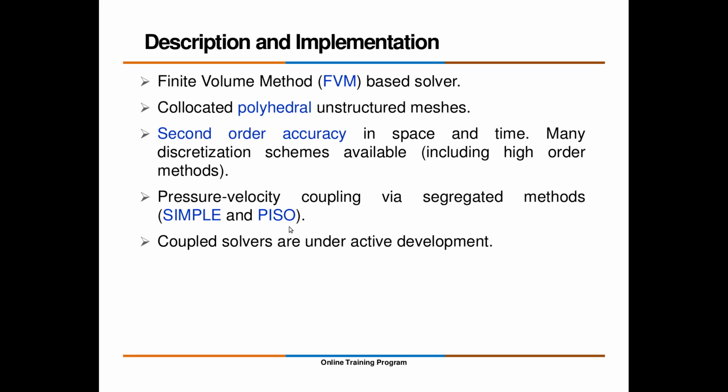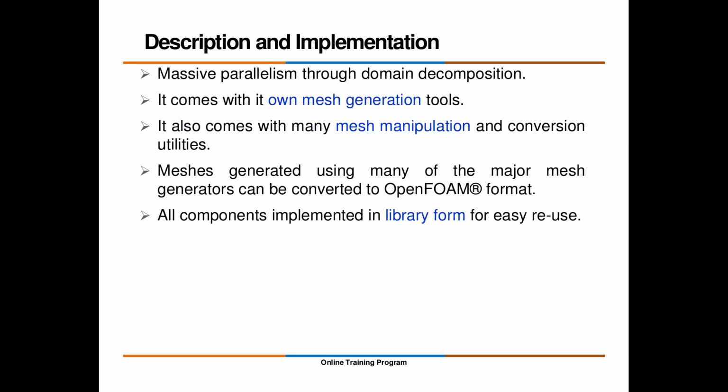These are all called iterative solvers, where step by step we iteratively try to solve one equation after another. But when we talk about a coupled solver, the Navier-Stokes and energy equations are solved together at a time, so it is a much faster solver. It is parallel by default, so you can run OpenFOAM either in a shared memory or a distributed memory environment.